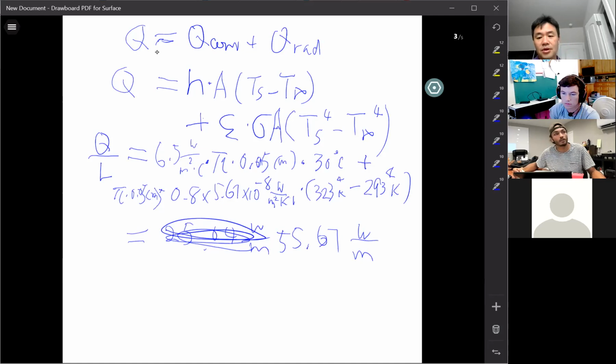So it's not conduction because of the insulation? Yeah, the insulation part is the conduction. When the conduction goes through the insulation, it will be equal to the convection going out of the insulation. That's the equation you should start from. I think the difficult part for that problem is the conduction, because it's a cylindrical coordinate. Your insulation is like a ring.